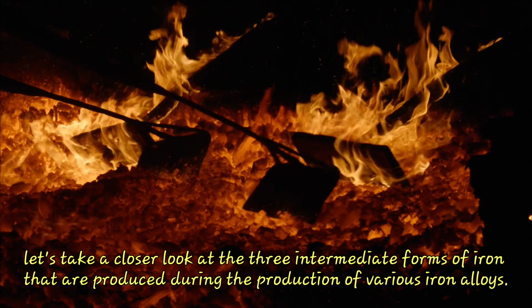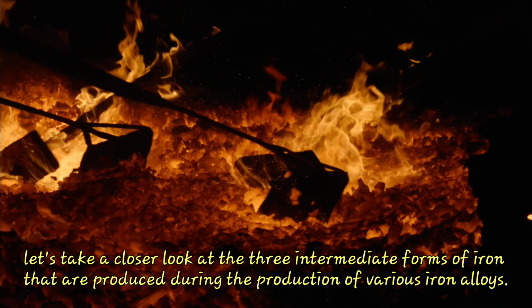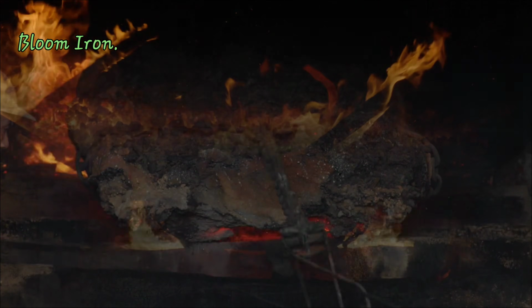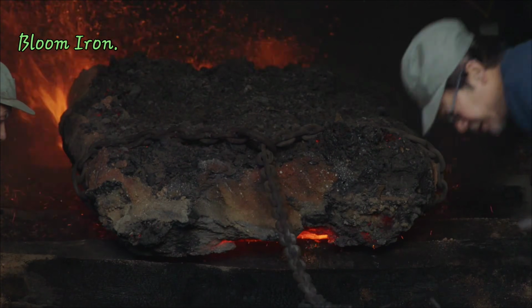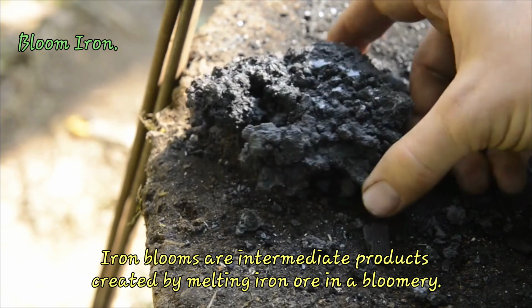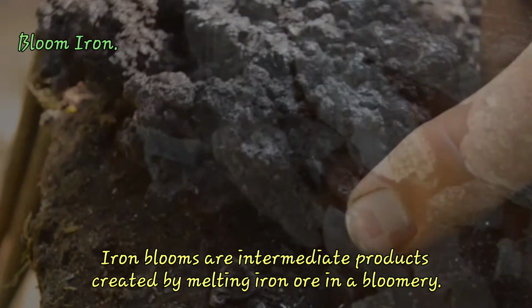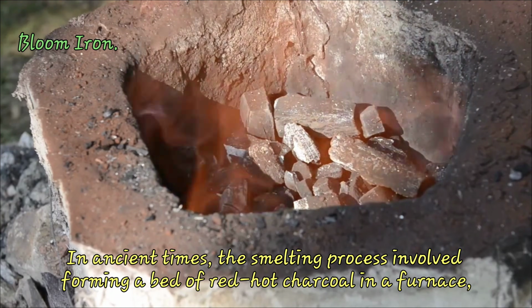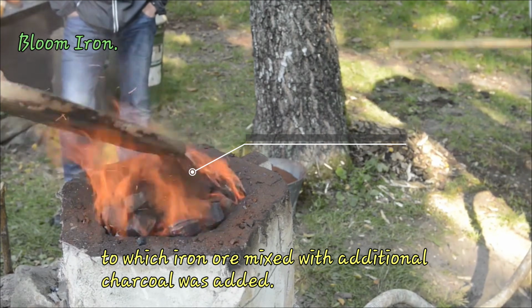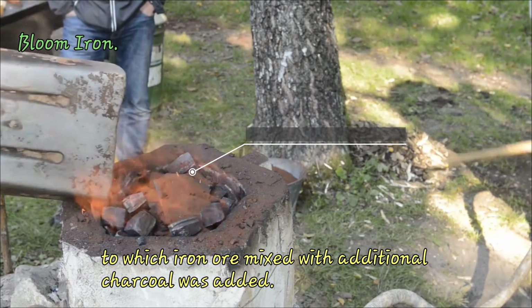Now that we've gotten background information on iron, let's take a closer look at the three intermediate forms of iron that are produced during the production of various iron alloys. 1. Bloom iron. Iron blooms are intermediate products created by melting iron ore in a bloomery. In ancient times, the smelting process involved forming a bed of red-hot charcoal in a furnace, to which iron ore mixed with additional charcoal was added.